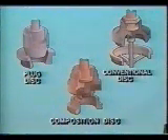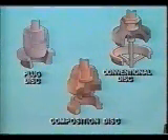Globe valves can be equipped with several types of discs, including the plug disc, the composition disc, and the conventional disc. The plug disc is the most common globe valve disc, and it comes in a variety of styles depending on its service. Composition discs are made of a flexible rubber-like material so that hard particles from the flow will not prevent a tight closing. Conventional discs are constructed of hard materials like metal or ceramics. Contact between the two hard surfaces will often break up particles deposited by the flow.